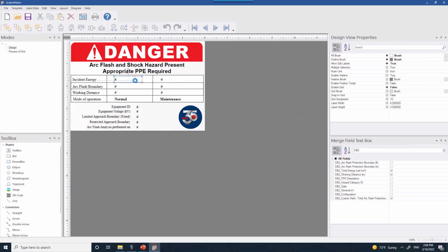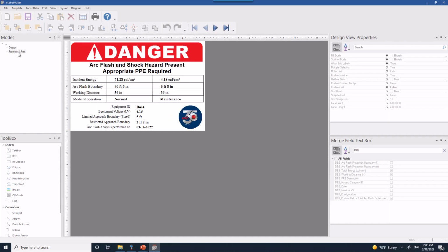Now, after selecting all of them using all the formatting tools, all the design tools, and all the grouping and alignment options, if you click on the print preview, this gives a clear picture of what happens when the maintenance mode is off, the incident energy value, and what is the maintenance mode on incident energy value. And the mode of operation is clearly listed, so the worker could easily identify the type of PPE and the clothing that needs to be worn for either of those 2 modes of operation. And this could be done for all the records selected in that particular set of labels.